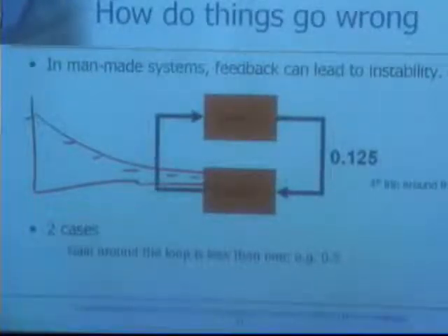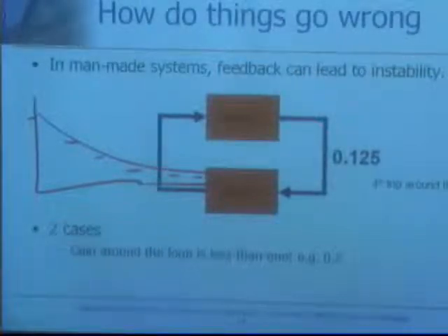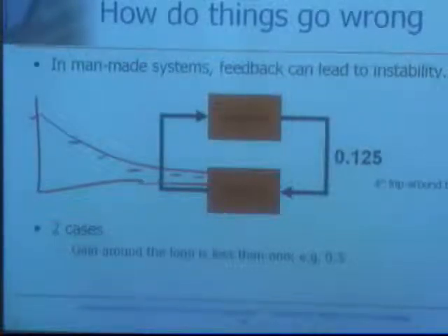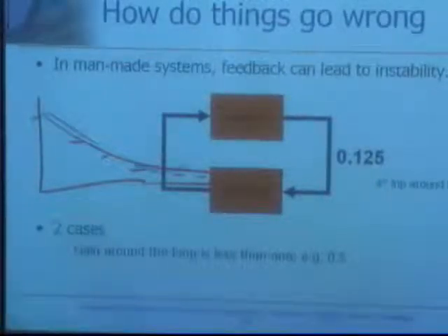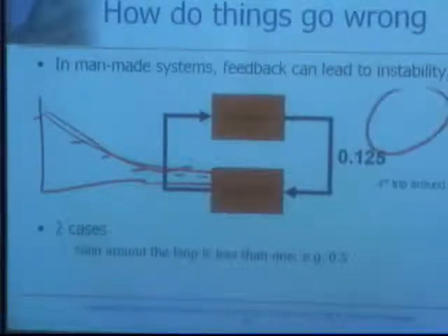I could shift what I consider 0. I could shift my equilibrium point, much like in the cruise control example. I inject an external signal, my 65 miles an hour, which is a shift away. That's what my 0 point is. So as I die down to 0, that means I'm actually converging to this desired external signal. So this is the good case.